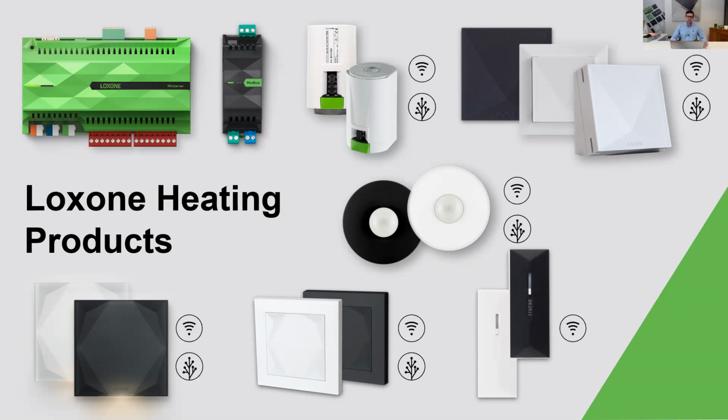In addition to this, I've also put our Modbus extension there. For anyone that doesn't know, Modbus is a standardization of communication over RS485. It's very common within many different control systems. You will see Modbus quite frequently on things like air conditioning units, heat pumps, and MVHR units. It's a common communication protocol for those kinds of peripherals, and we can speak Modbus through the use of our Modbus extension. So you could nicely tie in the customer's MVHR system, heat pump, and aircon units into the overall Loxone solution.